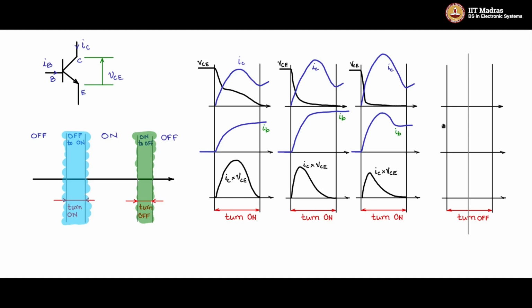So now look at the base current. The base current was at this level, and then I'm going to initiate turn off of the base current. So the base current is turned off. Actually you are removing the base drive, but the base current then starts going negative, meaning there is some base charge which is removed from the base of the transistor.